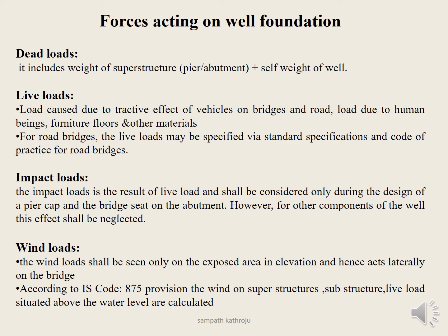Forces acting on the well foundation. What are all the forces on the well foundation? First is dead loads. It includes the weight of superstructure, pier and abutment, plus self-weight of the well. Live loads. What are the live loads? The load caused due to tractive effect of the vehicles, or the vehicle load also, and human beings, furniture of the floor and other materials which are kept on the bridge also. They are coming as live loads. For road bridges, the live loads may be specified by standard specifications and code of practice for road bridges.